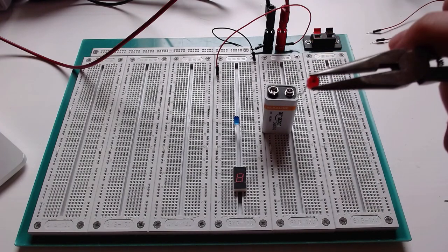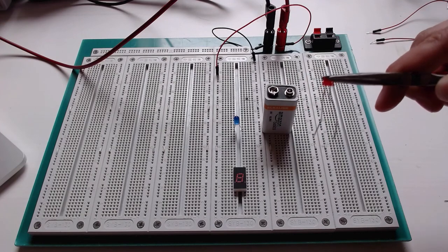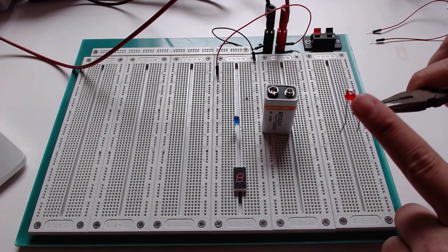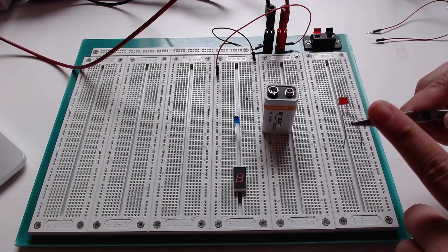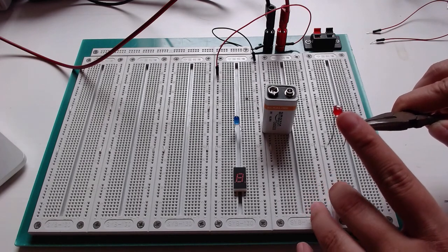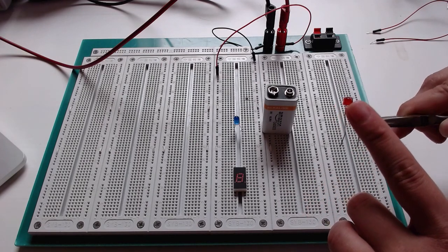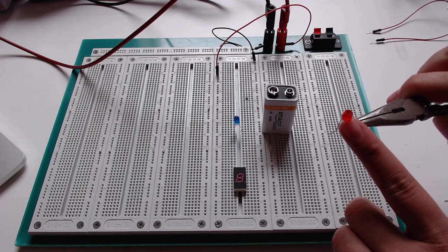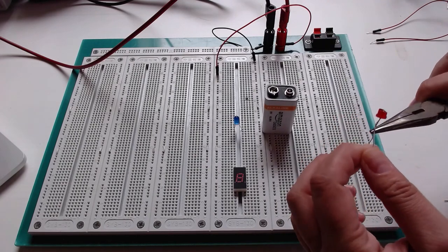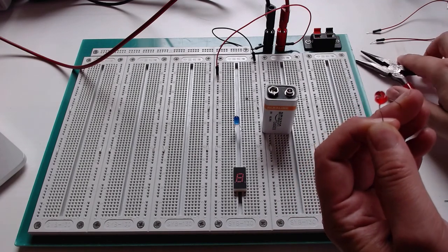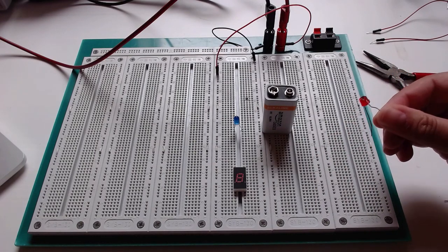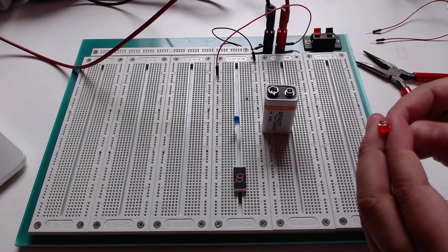yeah, that might happen. Okay, so a piece of this LED shot clear across my room because I overheated the LED by overvolting it. And it's not really the voltage that kills anything, it's the current. So I had too much current flowing through here, so too much power was being dissipated, it heated up, and it melted, and in a couple days when I'm sweeping the floor, I'm going to wonder what this little epoxy cap is doing. It also smells pretty bad, okay? So we want to make sure that we use a current limiting resistor with an LED so that we can prevent catastrophes like these happening.